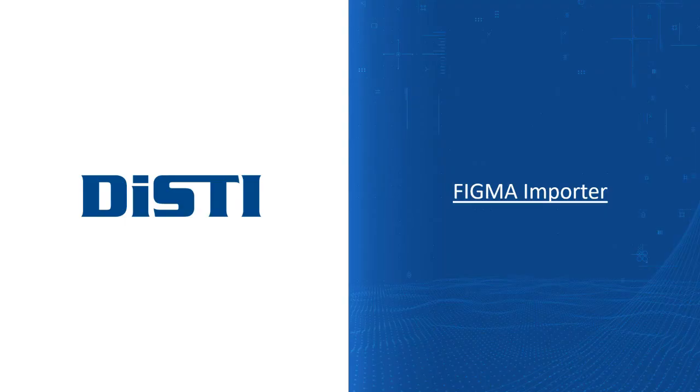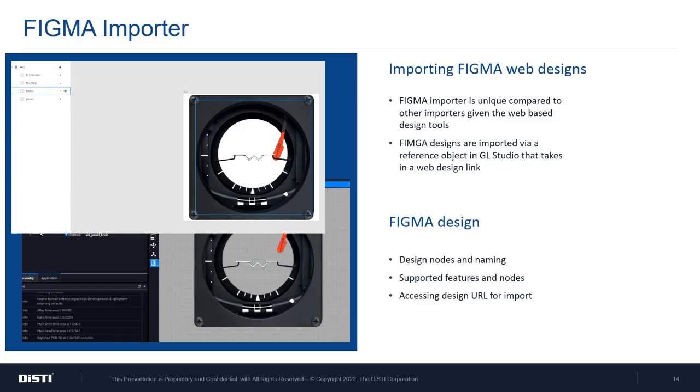Now, the next importer that I'd like to cover is our Figma importers. This is one of our more recently added ones. Figma Importer is a little bit unique compared to some other importers, given that Figma is a web-based design tool. So there's not really any files to drag and drop into GL Studio. So instead of dragging and dropping files into GL Studio, what you'll do is you'll create a reference object in GL Studio that already has all the scripts and everything that you need to import applied to it. And you'll give it a web URL for wherever your design is going to exist. And it will automatically import that file for you and update the design based on whatever parameters that you give it.